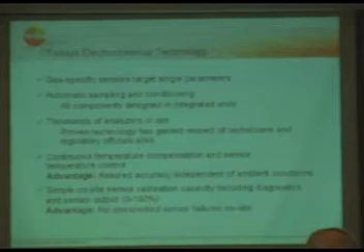The advantage is that every electrochemical sensor has a lifetime between 2 and 5 years. To make sure you are not going out on site, doing a measurement, and all of a sudden the sensor fails, with the calibration gas you can readjust the sensor, and then the analyzer calculates the remaining lifetime of the sensor in percentage.